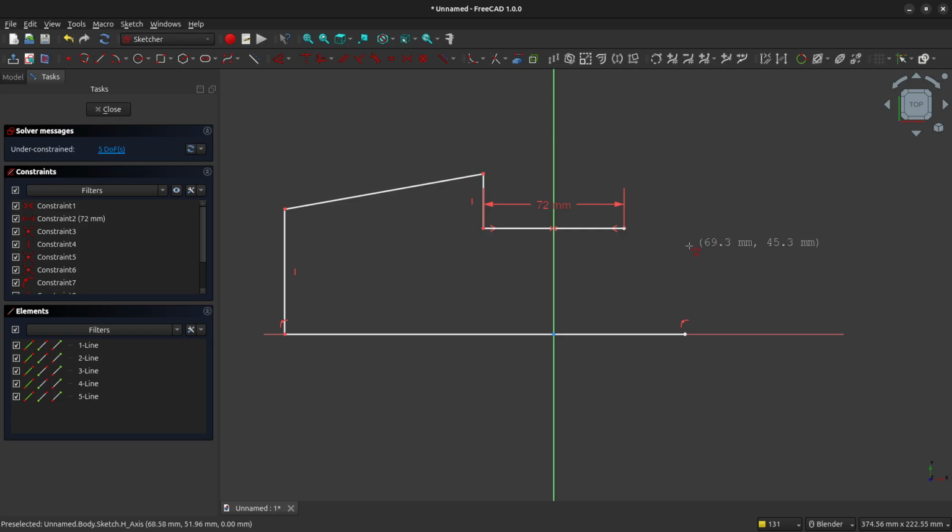That cancels the polyline. And now I'm going to come back up to the right-hand side of that line segment I created earlier. Left-click to create a continuing polyline from that point. I'm going to go up to approximately the same height as the line on the other side, and I'm going to come over a short distance. I'm going to right-click now to stop the polyline, right-click again to clear the tool.